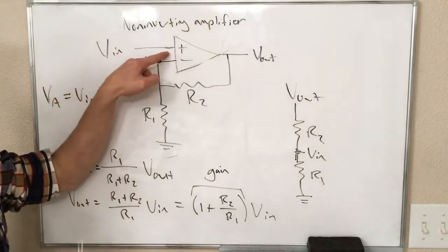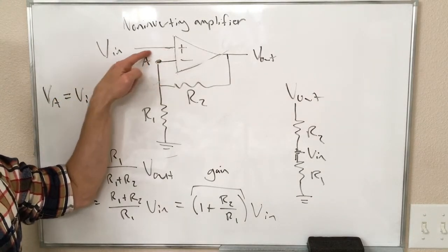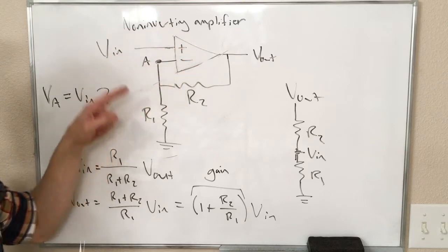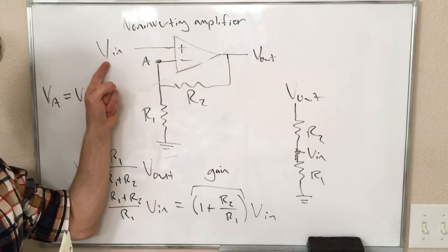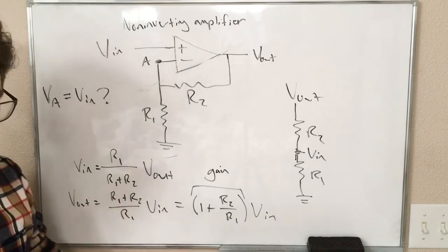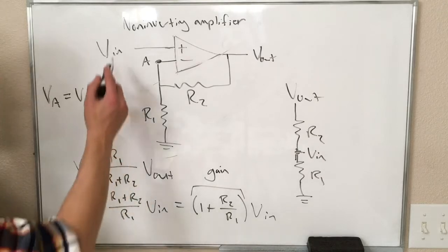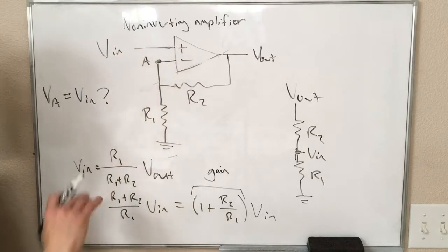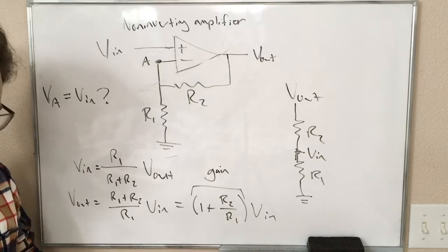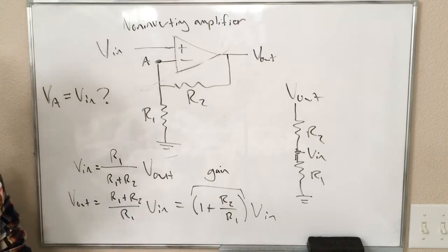Here, our input goes directly to the input of the Opamp where no current is supposed to flow. So this setup will require much, much less current from the input voltage source, whatever it is, because of that. So that can be an advantage. It can be a disadvantage because that can make this sensitive to certain kinds of noise also. But that is at least a difference to be aware of.